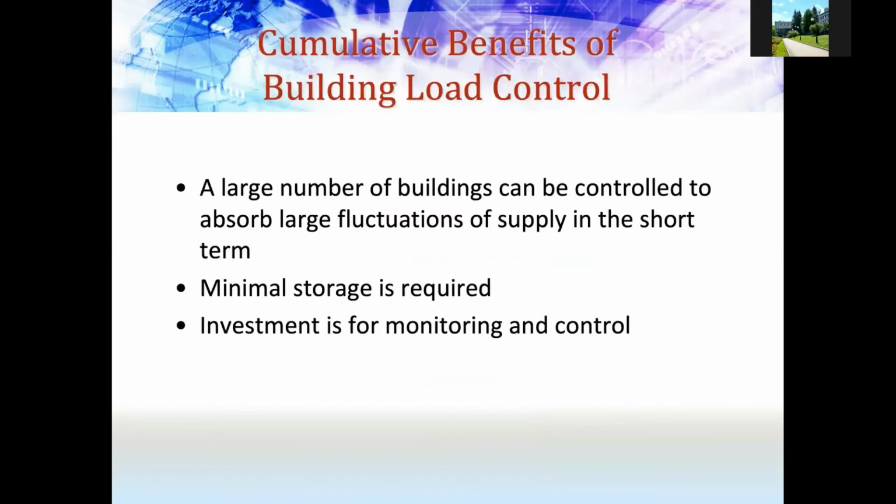Okay. Now, that was one building. If I have a campus situation, I have a large number of buildings which can be controlled selectively to absorb these fluctuations of power from, let's say, a solar rooftop system. If I do that carefully, I don't need to put a storage battery in every building. I can put batteries in some buildings, but I take advantage of my flexibility in demand to reduce the need for storage. That's why I say minimal storage is required.